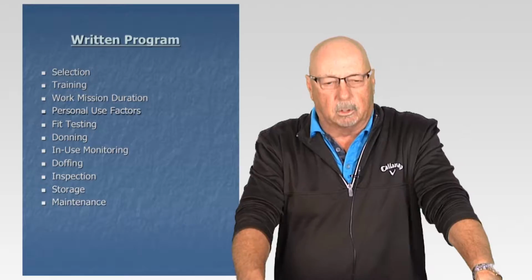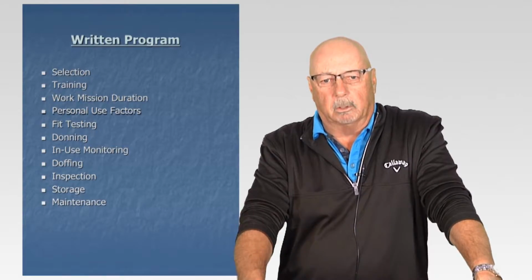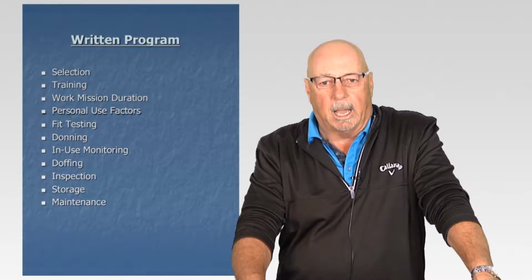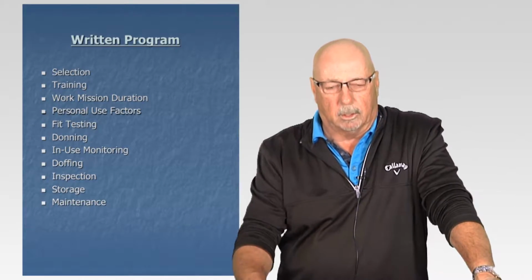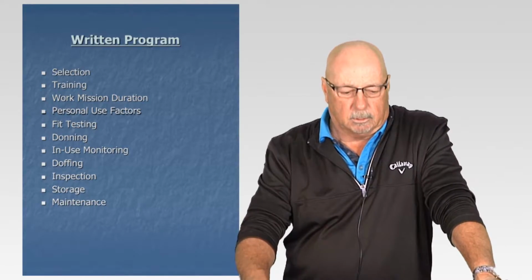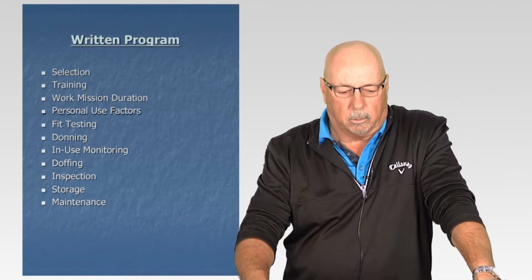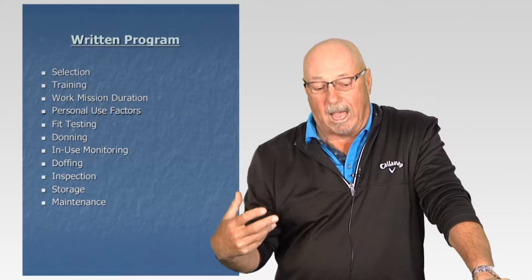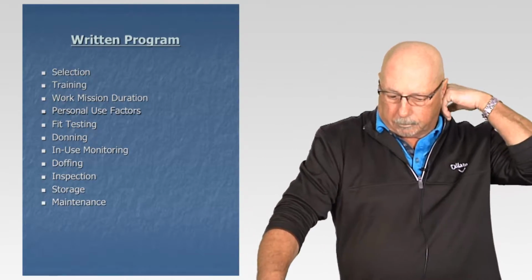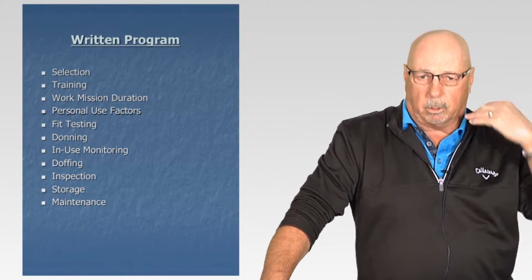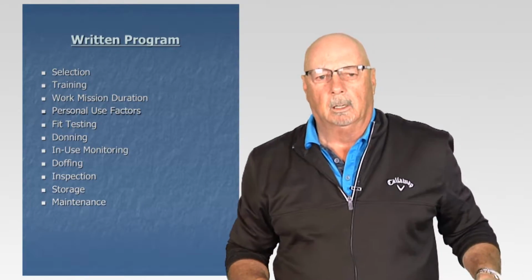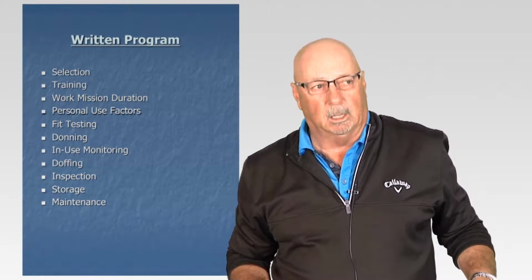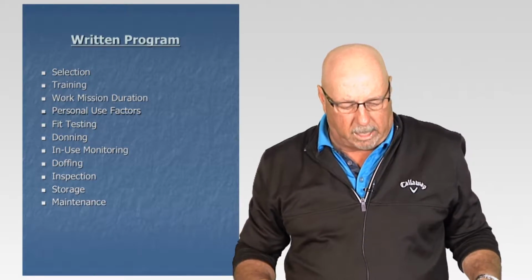Then your program's going to talk about the proper way to put the respirator on or donning the respirator, and how to wear it in use to make sure that it is offering you adequate protection, and then how to remove the respirator or doffing the respirator. And then what you need to do personally to inspect the respirator to make sure that it is in good working order, that it's not missing any parts, it's not damaged in any way.